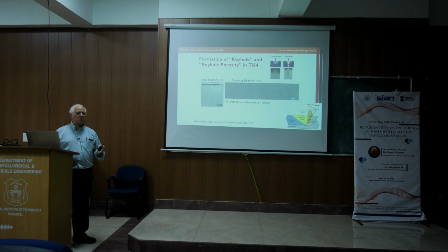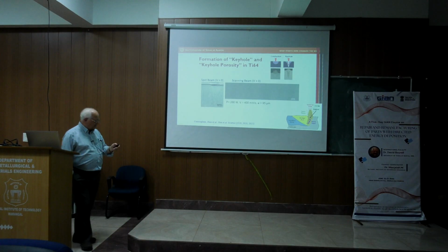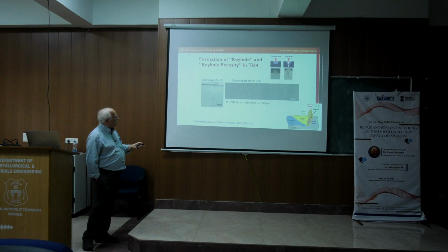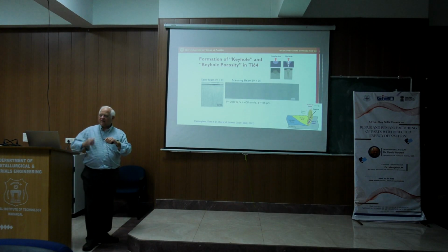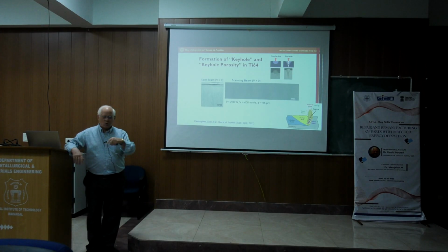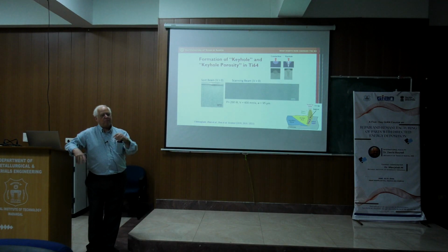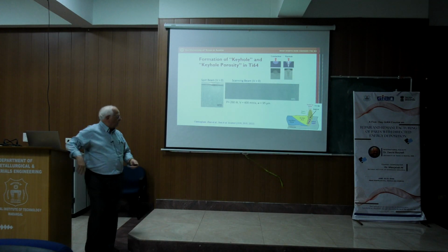Notice there's no porosity anywhere. The issue is, it's going to occur when I show you this one. It has to do with the fact that in additive manufacturing, we're actually moving the laser. So what we do is we move the keyhole, and that moves the melt pool in a way that looks like this.